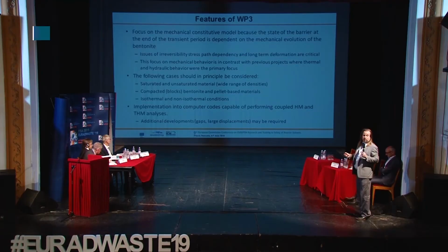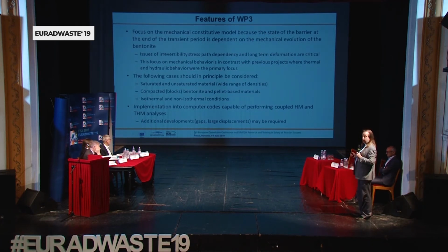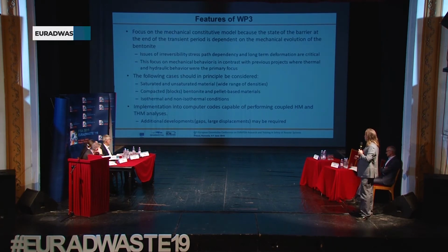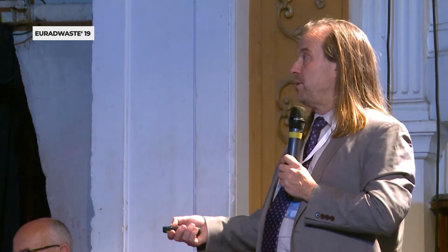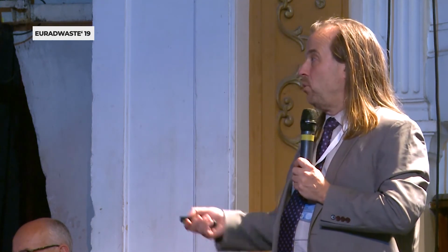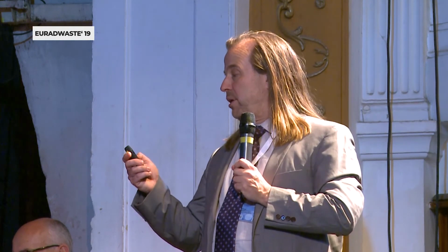If you look at PEBS, for example, which was a predecessor to Beacon, the TH processes were the dominant ones. And you should be able to consider saturated, unsaturated material, compacted blocks and pellet-based, isothermal and non-isothermal conditions, and this needs to be implemented in computer codes capable of performing coupled HM and THM analysis.